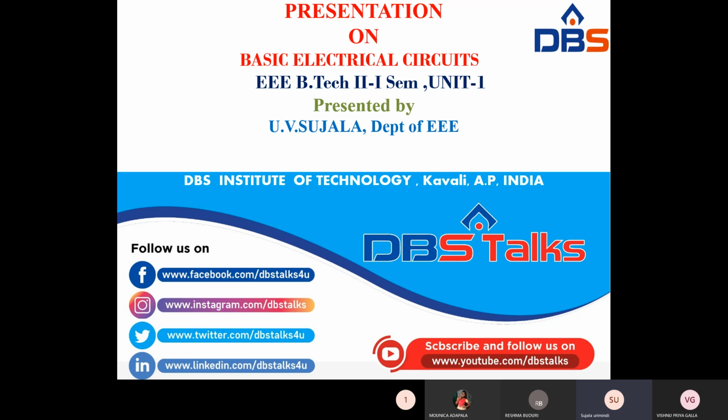Why is Kirchhoff's voltage law called loop analysis? Here the basis is that we find Kirchhoff's voltage law with respect to a loop. A loop means it starts at one point and returns back to the same point. So Kirchhoff's voltage law means the algebraic sum of the voltages is equal to 0, and it is also called mesh analysis and loop analysis.